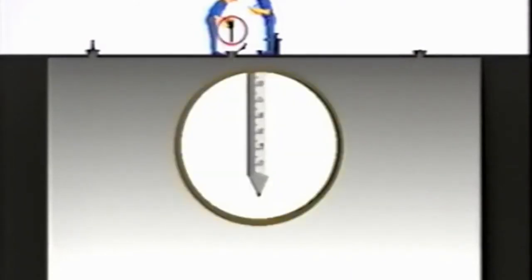If there is sludge or sediment found in the tank, take an average and use the innage table to find the volume. If there is a volume of oil in the aft part of the tank, and a layer of 1 centimetre sludge or sediment is found in the most forward part, it's reasonable to argue that 1 centimetre of sediment covers the whole bottom and should be deducted from the volume of oil left.